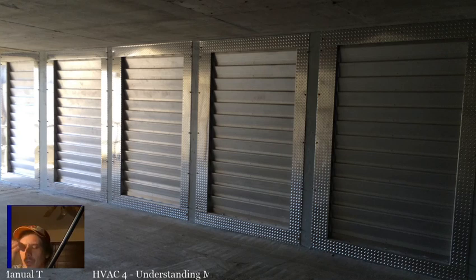But generally, the reason we want a low temperature rise is to protect the integrity of the heat exchanger and the components of the flue. It's not necessarily because we're going to have carbon monoxide or condensation or anything like that. Now, too low a flue gas temperature can cause condensation, but higher flue temperatures aren't necessarily the worst thing in the world. Especially on natural draft equipment, it's going to be relatively normal to have a high temperature rise, but you could end up with damage to your heat exchanger or something like that.